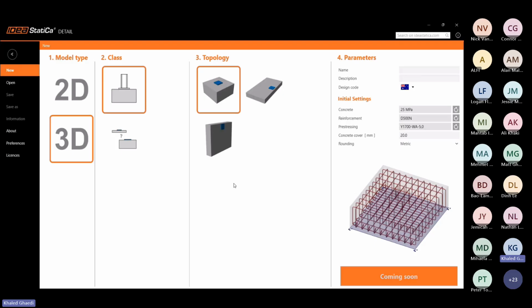In terms of the anchorage, you can see the bond stress, you can see the forces, you can go for checking the utilization ratio for the bond stress and also for the total force that you applied, and then you can go for nonlinear deformation of the base plate. Here you can just play with the scales. Since right now we are in the 3D detail, you now have actual 3-dimensional stresses and strains, and you can check these stresses as well. Let's say the stress in tension, compression, and so on and so forth.